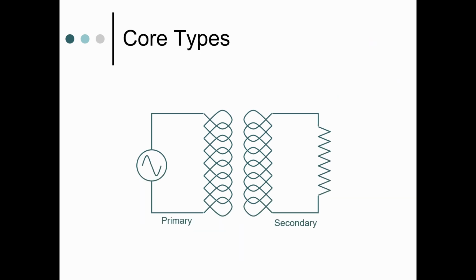The primary coil is an electromagnet that has a collapsing and expanding magnetic field surrounding it. Early on, it was discovered that electromagnets could be made more efficient by placing a ferrous, iron-like metal bar down the center of the coil. Addition of the metal bar down the center of the primary and secondary coils makes transformers more effective. More of the electrical energy used to power the primary is transferred to the secondary side of the circuit.